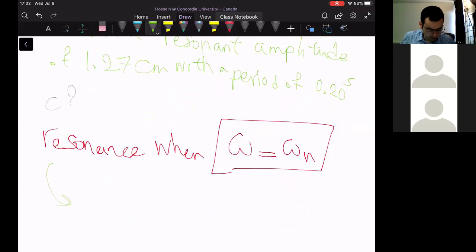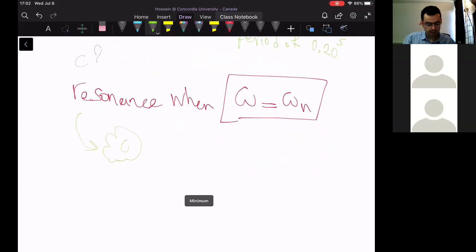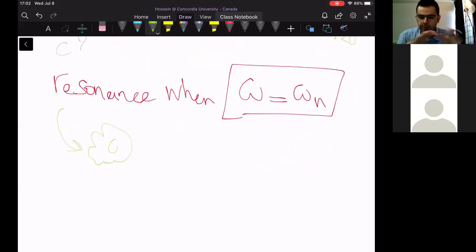In this case, at resonance, we basically need damping in our system. Of course, we use damping in other cases, but at resonance specifically it is our only tool. So we always have to consider some percentage of damping in our system in case of resonance, because when we design a mechanical system, for example a bridge, we don't know the main frequency of wind that will hit the bridge, and also in case of airplanes, everything.